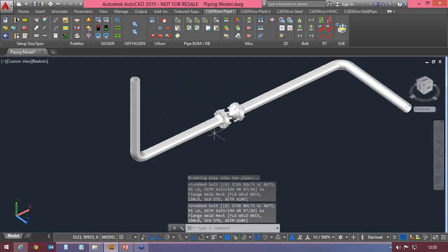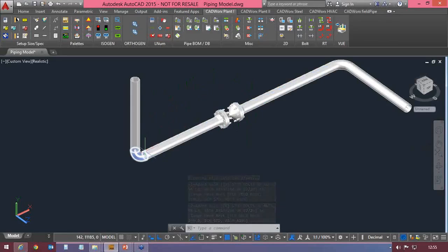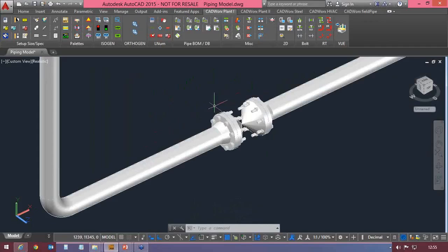Now this component is placed at a distance of 1200 from the endpoint of this valve, because I have taken the reference distance as 200, and then I have defined the component insertion location as 1000. So it is 1200 distance now. And also here you see